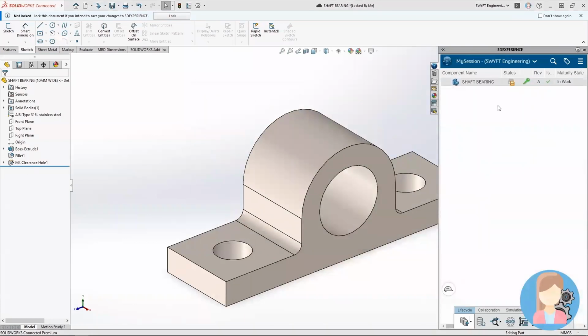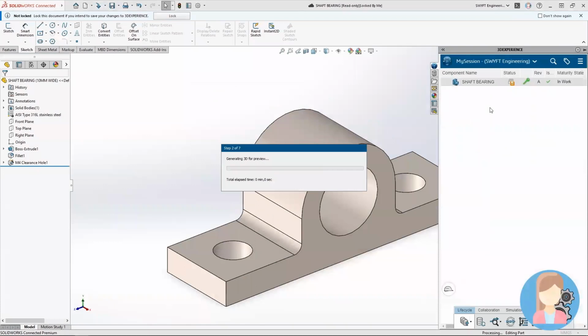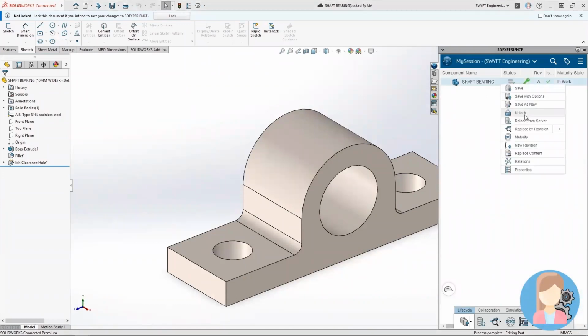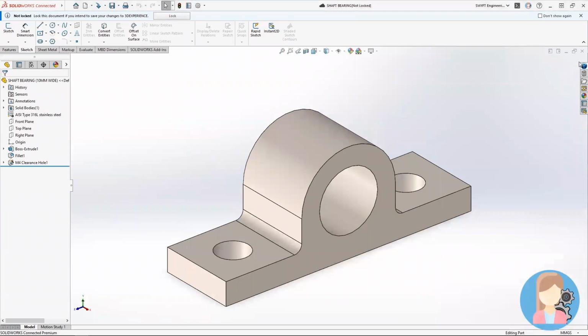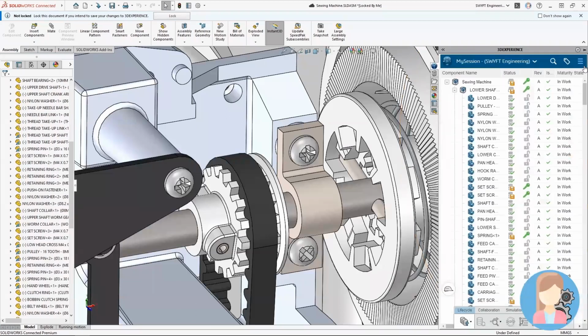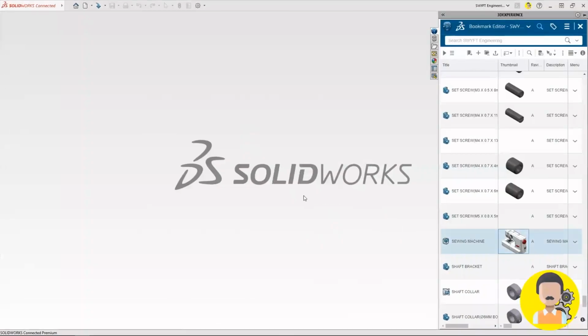What this will do is then, and technically, in this case, even if I had it open in my computer's memory, as I showed in the first example, it would have a similar outcome as this replace command. So in this case, that is now checked into that system. Same thing happens when you go to the assembly, it updates it. You can then check that assembly into the system as well to make sure everyone else that has access to that has the latest version.